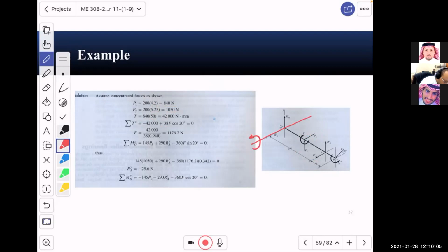So we will sum up the moment along the Z. This is Mz at point O. What are the forces? In red, this one, Py, RA along the y, and of course the radial direction force coming from the gear. Good. We know their distances. This one is located at a distance of what? 200 divided by 2. The roller is 200. We divide by 2 because it's acting in the middle of it. That's 100. And then plus 45. So that's why we have 145 multiplied by Py.